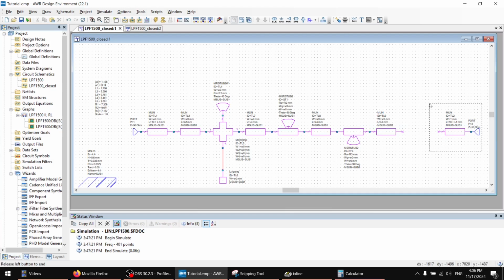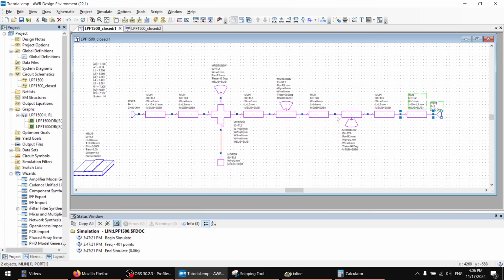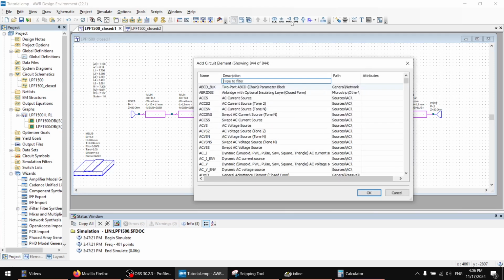Now, there's one component that might come in handy if you are working with much higher frequencies and the difference in the widths of the components. Actually, some people recommend this in electromagnetic simulation to terminate every change step of the width. I will not do this here, but if you want to be really academically correct about this, there is something that is called the taper.